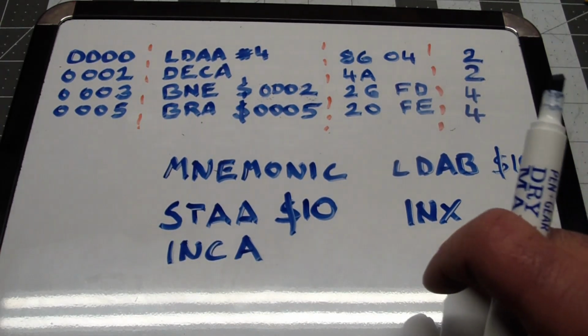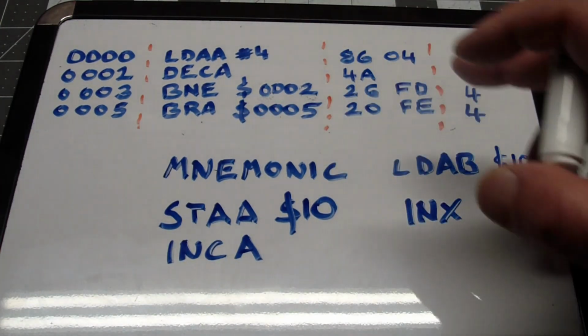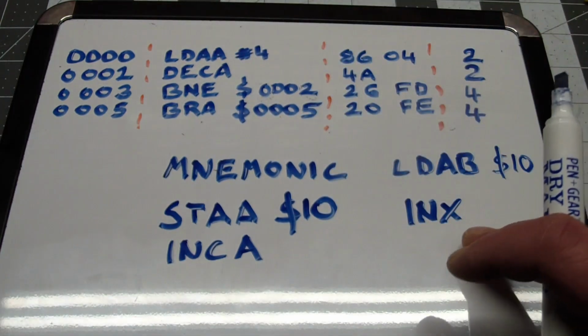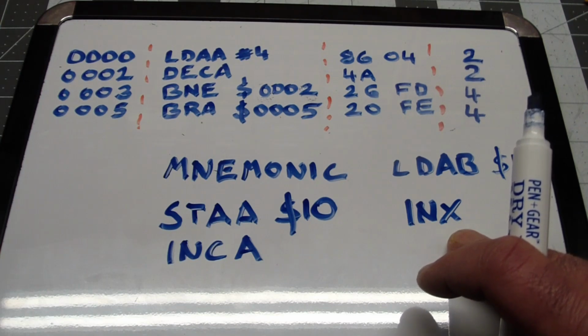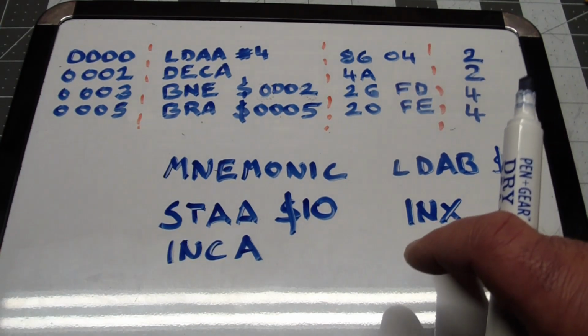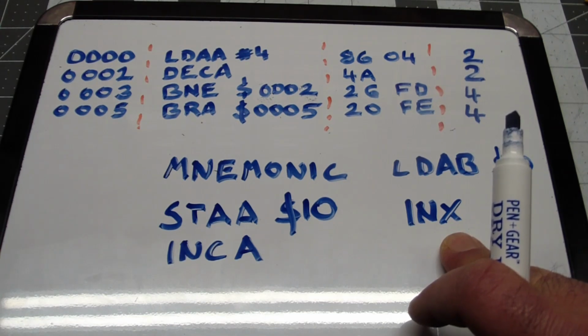And in this case, we can still do a branch not equal or a branch on plus or whatever after this, but instead of looking at bit 7, starting from 0 of course, it will look at bit 15 in 16-bit registers to set the condition codes.